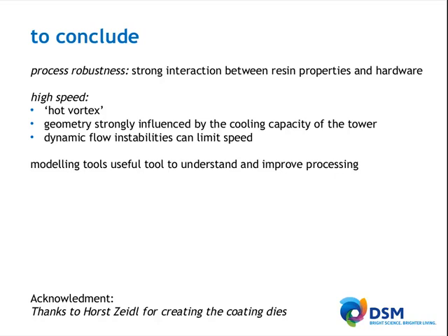Can the interface instabilities even lead to bubbles, nodes, or delamination? No, I don't believe so. There is no entrainment of gas inside these coatings. They adhere quite well. The only way that it could lead to cavitation is when you create cavities inside the coating die, and I don't see the pressures dropping that much inside the dies by itself.